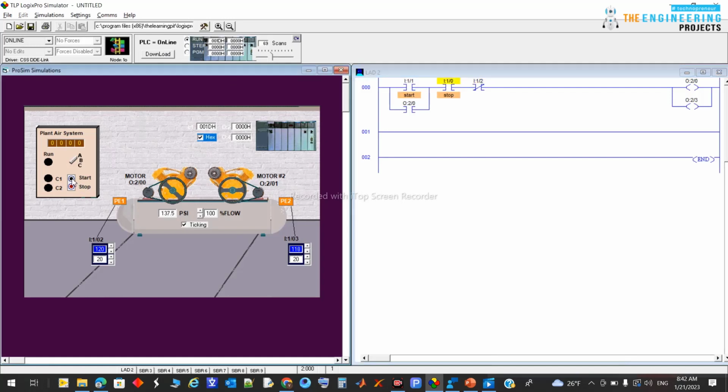As you can see here, because I am trying to start, but because it is above the threshold value, which is 120, this input is now on and prevents the motor from running. Once it reaches less than 100 and I click start, okay, still not working until reaching the low value, which is 20. So by having this value, it will run again. So let's see.